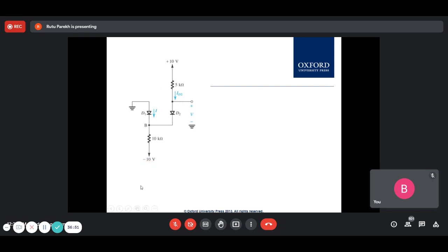Be very attentive. You know where I is here. This is I, and this is V. So you find out I, and if you get the correct polarity, okay. If the diode is connected this way, then the current is flowing this way. If you get I positive, that means this polarity is correct. That means the diode connected this way is correct. Then your supposition is correct.